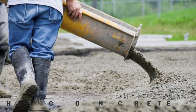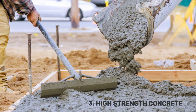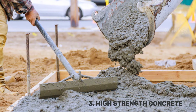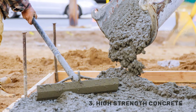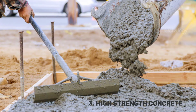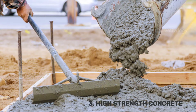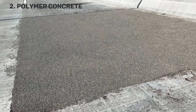Next, high strength concrete. High strength concrete is a concrete with strength over 40 Newton per mm square. It is also known as high performance concrete. High performance concrete is used to achieve some special properties in concrete like high strength, low shrinkage, self compaction, high fire resistance, etc.